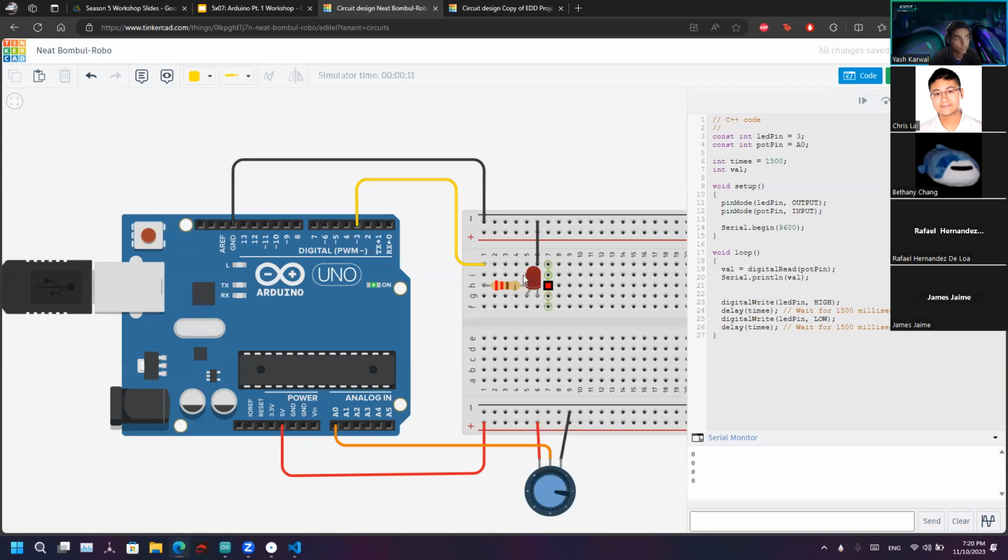It's going along with the actual blinking of the LED because of the delays that we have. Because the delay will actually stop the entire process of the Arduino since it's only one processor. So you've got to keep that in mind. You can't do long computation. It'll kind of hold everything back unless you know a bit more about how to optimize things.